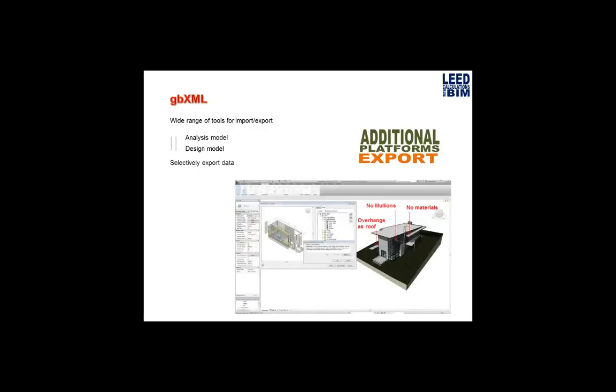The reason I recommend this method is because the GBXML schema is only going to recognize certain elements, namely system families: floors, walls, roofs, and rooms and spaces. So if you have overhangs in your model and you created them using a generic model family, they're not going to export, because the schema just doesn't recognize them. So you have to model them as a floor or a roof. It also looks at adjacencies differently, not as parameter designations. It looks at whether a room is interior or exterior based on what it's adjacent to. It has no way to recognize materials attached to a surface. I know you can create APIs to solve all of this, but if you're not customizing and you're using what's standard within Revit, you're going to need to use only system families.